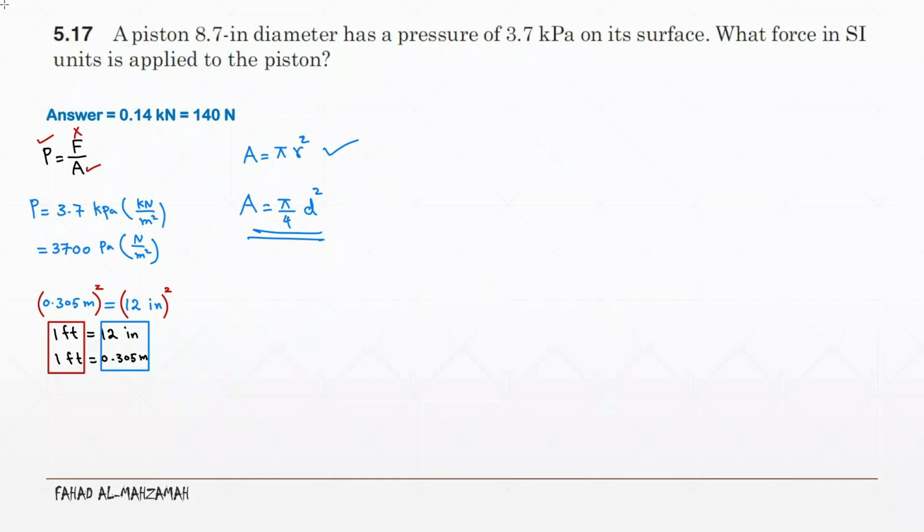What are the forces? The weight of the object, which acts downward, and the upward force, which is the buoyancy applied by the liquid. The buoyancy can be calculated by calculating the weight of the displaced liquid, not the whole liquid, only the liquid displaced by the object.